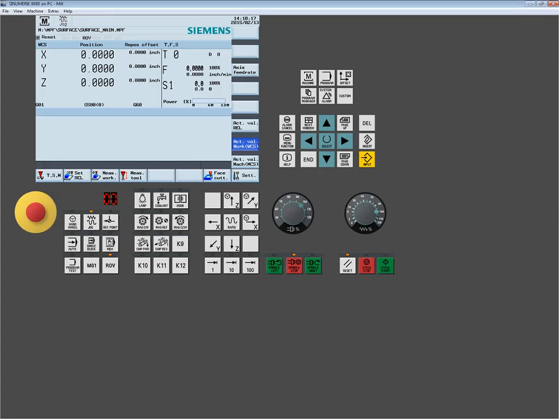All right. From there, what I want to do is transition over to my Program Manager section. Now, I'm navigating through the different screens with this keypad on the right side of the display. You're going to see my mouse hovering over it. With that, I can navigate back to the machine area. That's my jog screen by hitting machine. I can go right to whatever program was last edited with this program button, or for what I'm doing right now, I can select the Program Manager button, and that's going to get me to the area where all of my part programs exist.